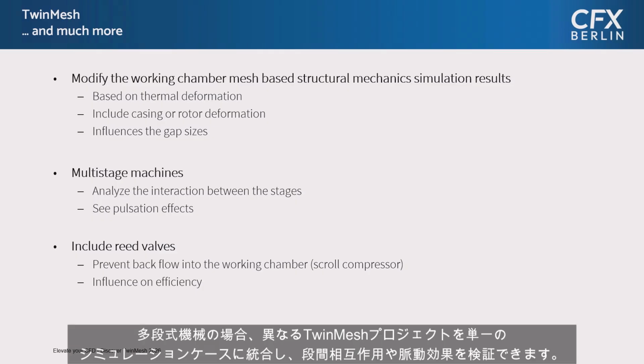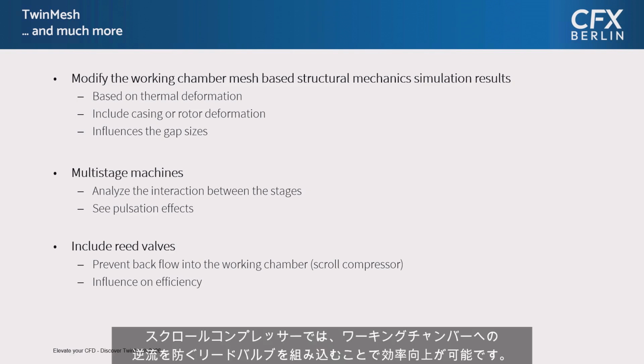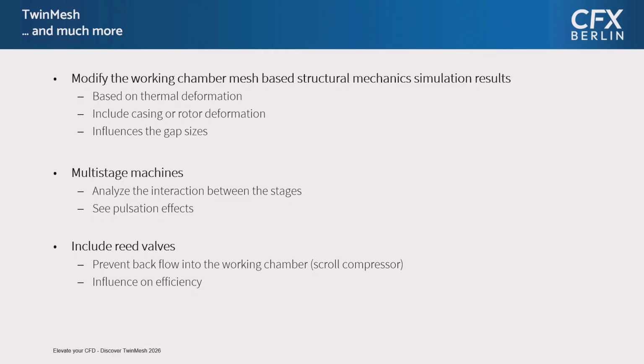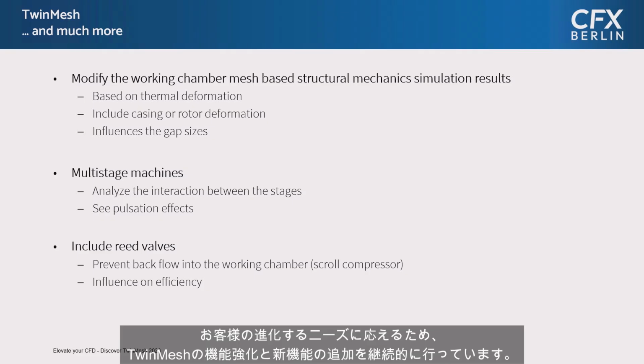For multi-stage machines, you can combine different TwinMesh projects into a single simulation case to study interstage interaction and pulsation effects. For scroll compressors, you can include reed valves to prevent backflow into the working chamber, which can improve efficiency. We are constantly enhancing TwinMesh and adding new capabilities to meet our customers' evolving needs.